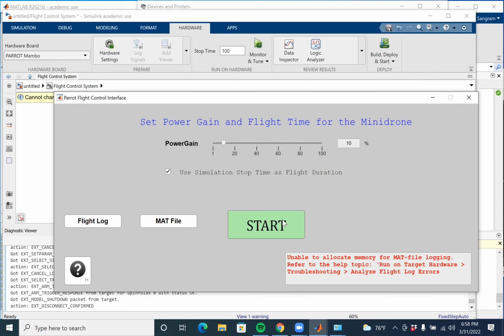So this is why. What should happen? When you have a negative pitch, when it's going down, motor 1 and motor 2 should speed up, and motor 4 and motor 3 should speed down.